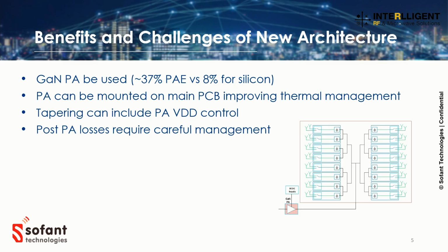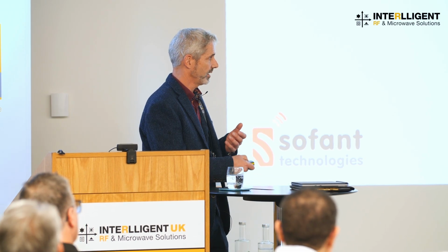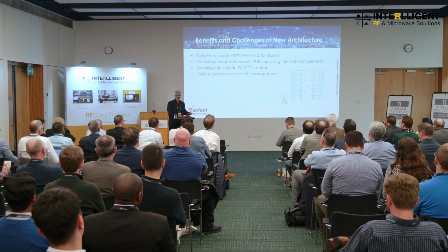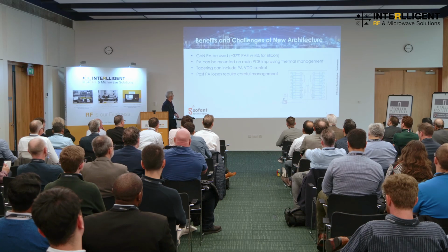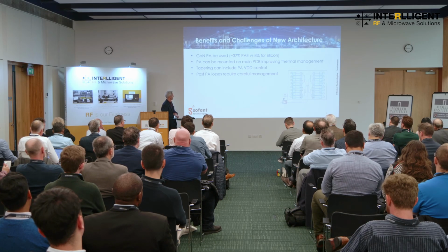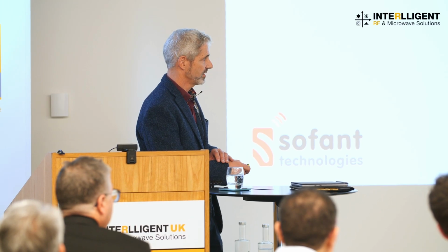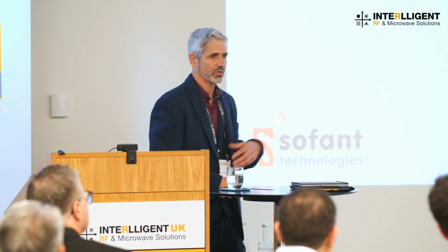The other thing, and I'll touch on it a bit later, is we've now moved the PA off the subassembly and it's now on our motherboard, so we can directly heat sink it to the chassis. That helps us with thermal management, and there are some other benefits I'll talk about later. I'll also talk about tapering and other linearization techniques later, but we have the ability here to apply tapering at the PA, which again saves some power.